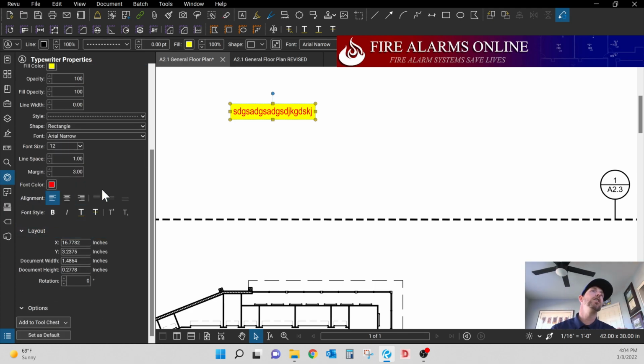And the nice thing to know here, keep this in mind when you get ready to set up your Bluebeam: if you like your text a specific way, or your callouts, your clouds, if you want your clouds to be blue instead of red or thicker, whatever, whenever you're editing any kind of properties here, always go down to the bottom and set it as your default right here.